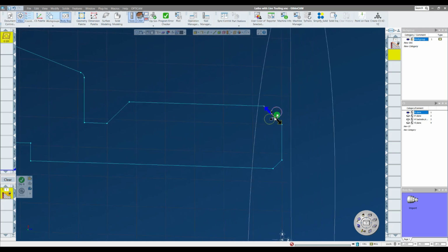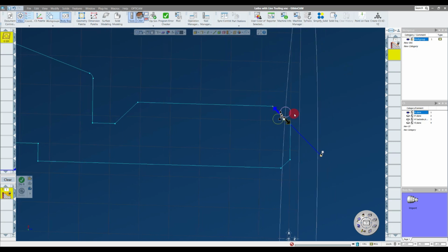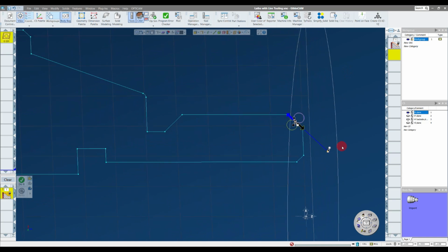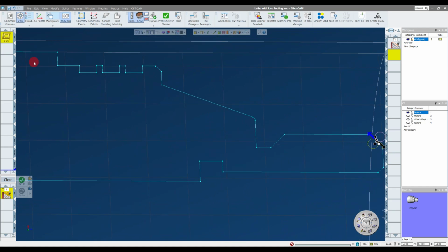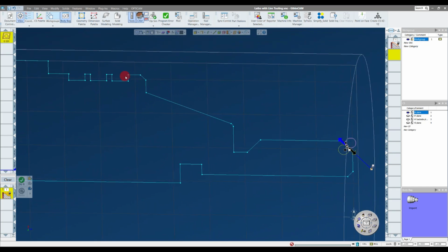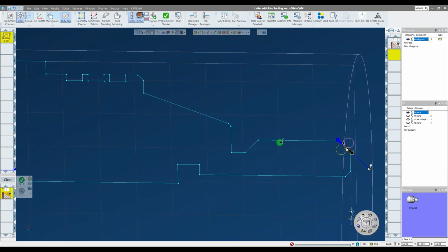I'm just going to simply drag this white circle down along this line, because remember we're selecting this line, so I can only click and drag this in line with that geometry. I couldn't drop it out here or anything. So I'm just going to drag this outside of the grid of my stock, and I need to set my end marker, which is my black square and my black circle, on this line. So I could manually drag this to whatever geometry I wanted to end on.